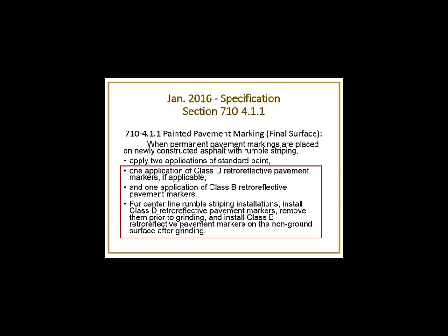Several years ago, we had some temporary markings and we weren't using them, so we took them out. So the only pavement markings that we had on our QPL were type A and type B. The type A was a temporary marking, but again, it was installed just like a permanent marking with hot bitumen. It's easy. And those markers really don't lend themselves to be taken up. You can get them up with an air hammer or a hammer and a bar. But even after you pull them up, there's an unsightly spot after you've removed it.